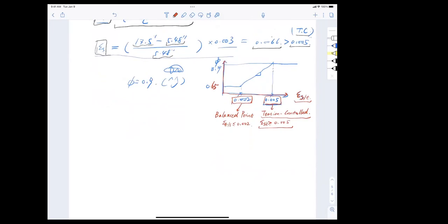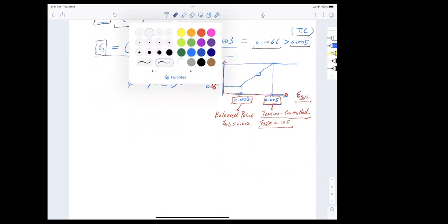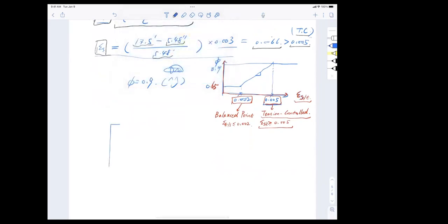Now you start to wonder, what does this have to do with my section strength? Well, here's a diagram, remember? You have this section here, with four number 8 bars, a width of 12 inches and a height of 20 inches. Remember, that is our section, right? And the strain diagram looks like this. At the top here, I have epsilon CU, and this, my friend, has been fixed.